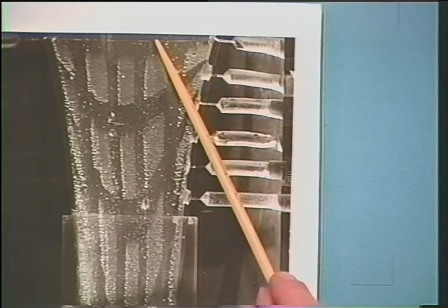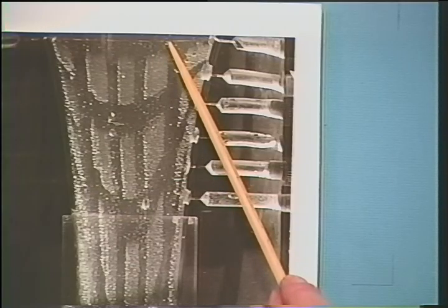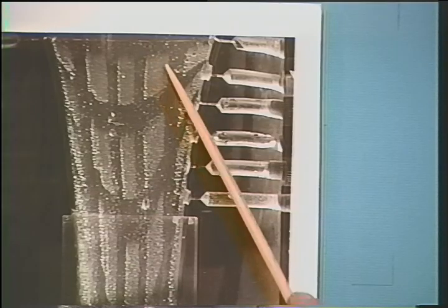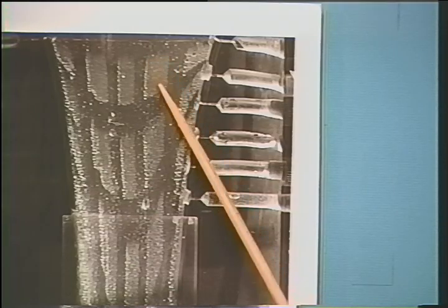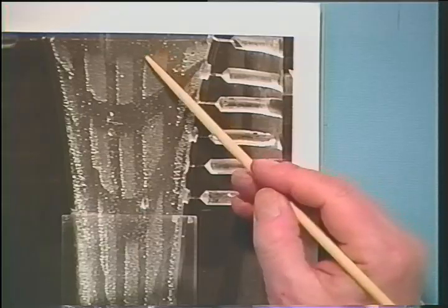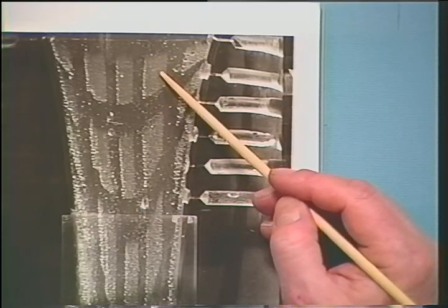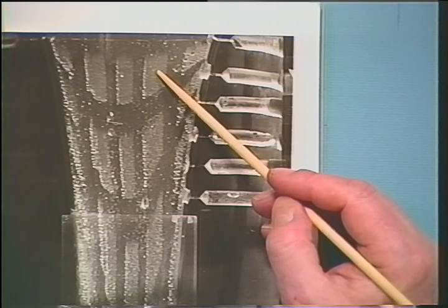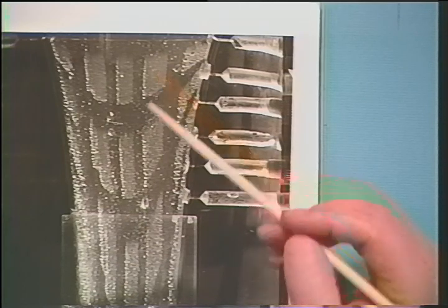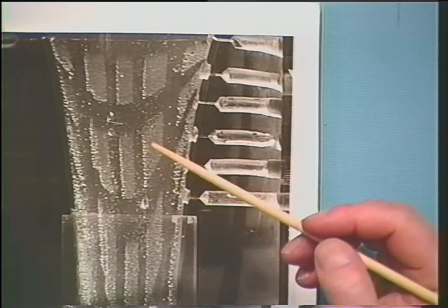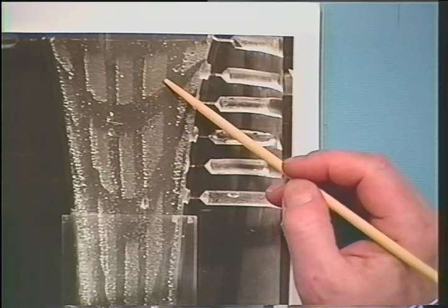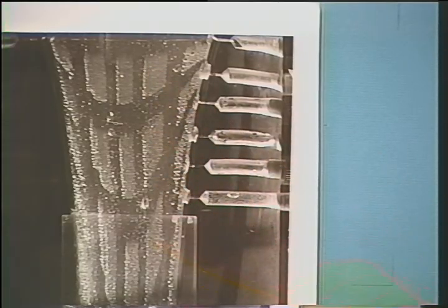There are parts of this wire being exposed freely, and when we run a current through this wire, we can produce bubbles, and those bubbles are used then as a marker. So bubbles are produced, and then at some time later, the bubbles are here. Now, we don't produce bubbles constantly. We do that like Indians give smoke signals in the movies. You know, we just release bubbles occasionally. So we have bubbles like this, and another burst of bubbles, another burst of bubbles.